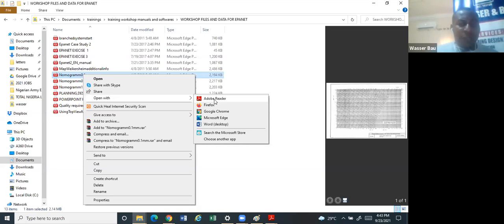For the velocity, the minimum acceptable velocity of flow in your network is about 0.3 meter per second. And the maximum is about 3 meters per second. So it's a factor of 10. Why do we say this? Because if the velocity is too low, let's say in the case of a sewer network, you're going to have deposition. It means that the water will not flow accordingly, and that could lead to siltation of the network.